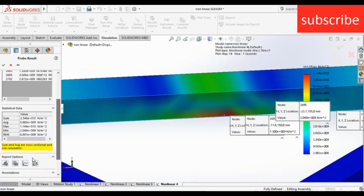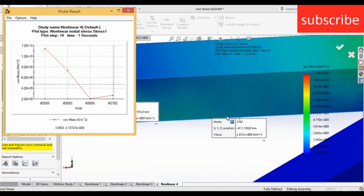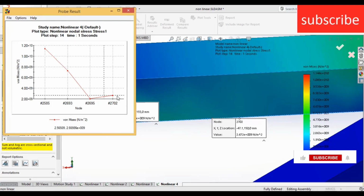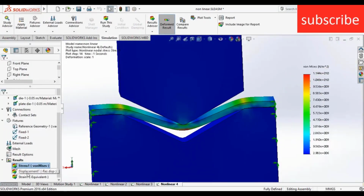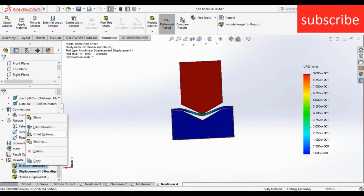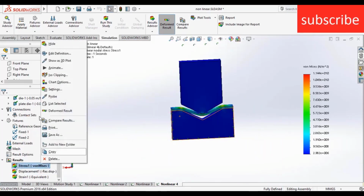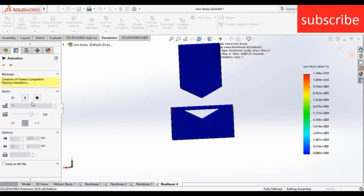Now go to probe. Here you can see the stress is maximum, and here stress is maximum, that is the first point. After that I go outwards and I accidentally select the top of the plate, because of that it shows the graph. I hope this video helps you, and you can do more things. For example, displacement show, and you can just click on animate so that you know what's the better result.